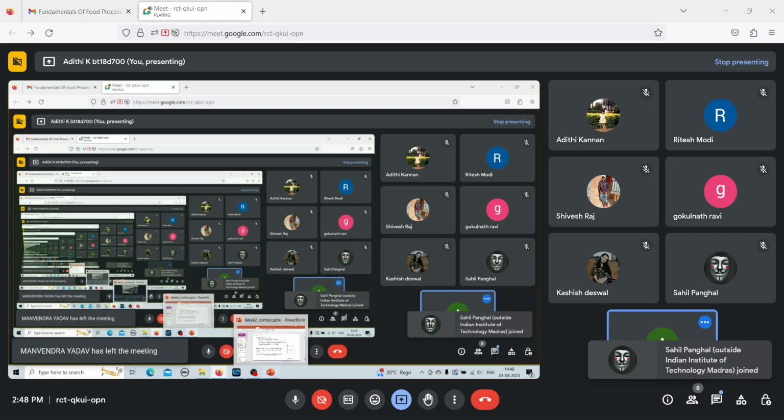On the contrary, if Deborah's number is greater than 1, it appears to be more elastic than viscous. The answer here is option A. Is this part clear? What Deborah's number means, what relaxation time means, and what does it mean to be more viscous or more elastic? Because this part of the viscoelasticity is the topic that has been discussed in 3 out of 5 lectures. So you need to understand properly what it means.